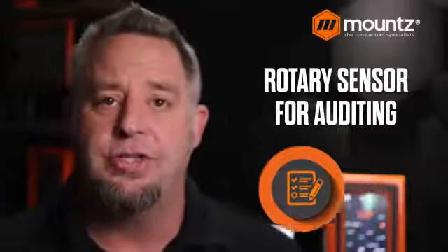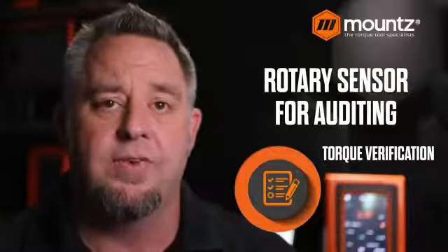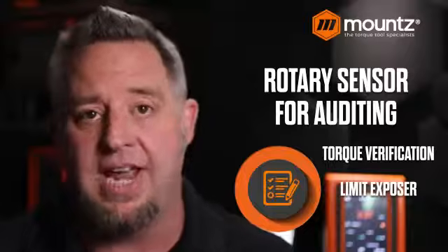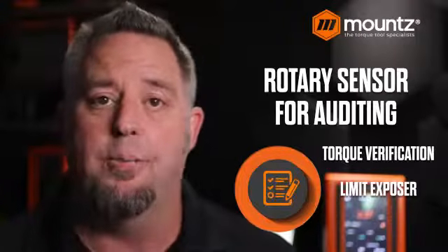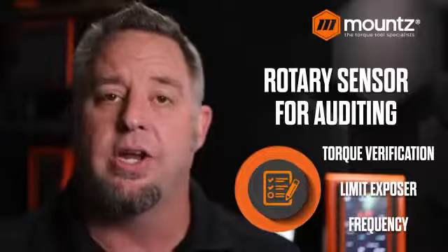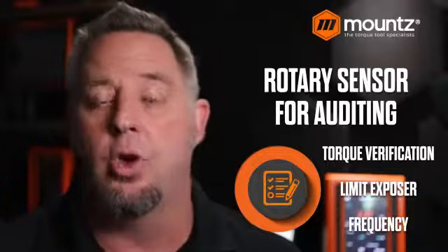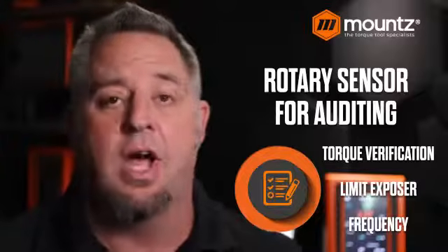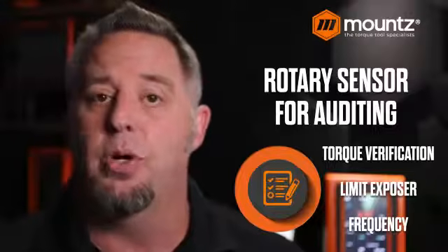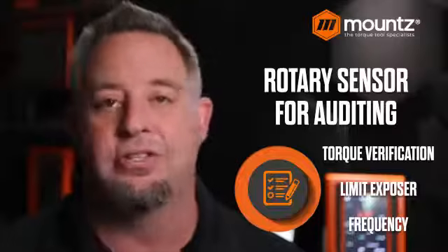If we want to use the rotary sensor for doing auditing or torque verification, this is by far probably the best case scenario for use. We can take a torque sensor out onto the factory floor. We can come to an operation, put the sensor between the tool and the part, go ahead and run that down and take a few readings and make sure that the tool is producing what it is supposed to be doing. And so with that, in conjunction with the torque analyzer, we can save those readings.